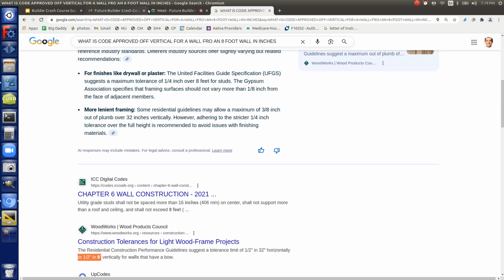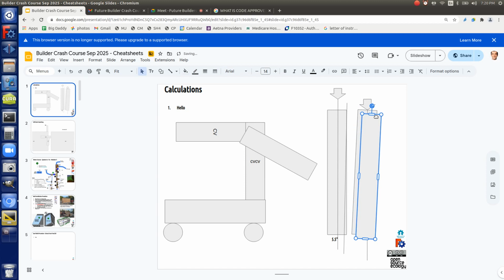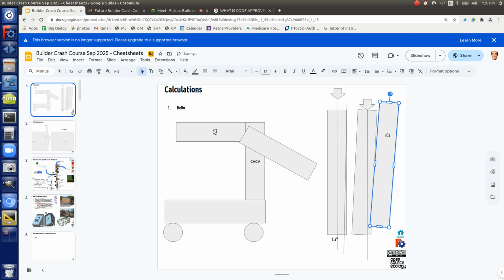But what's the danger zone here? Okay, here you're literally getting to where this wood is going to get crushed, because effectively only the part on this side of that line is catching all the force. If you bend it even more, you can reach a theoretical catastrophic limit. Say it's bent like that.